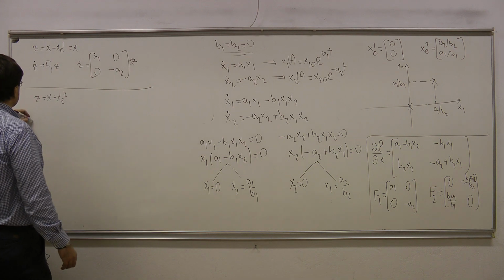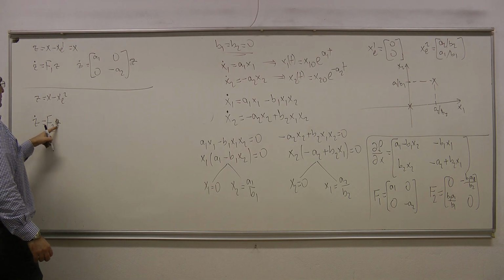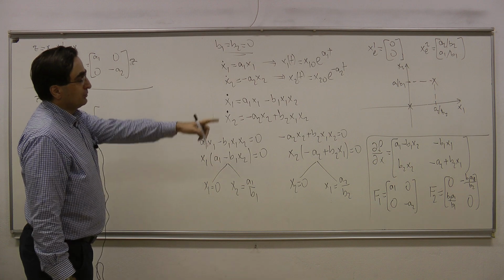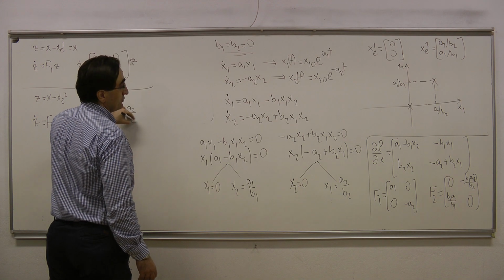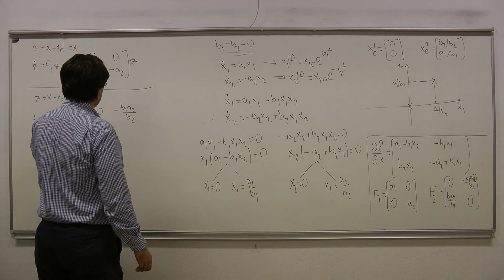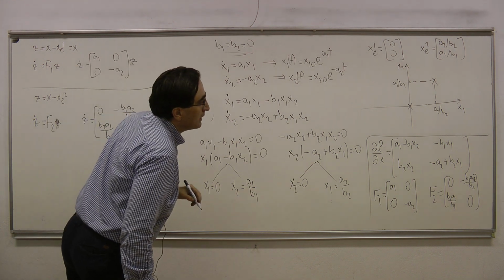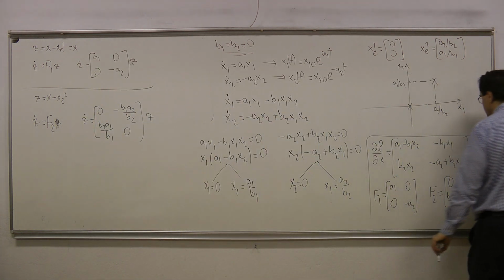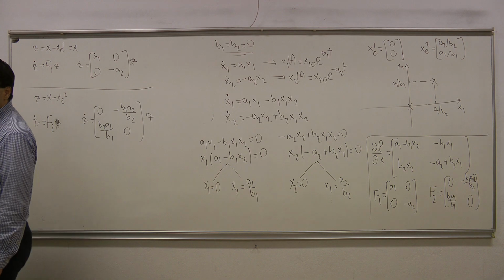What I have to do here is to write the dynamics around xe2, and that would be Z dot equals F2 Z, and we see here that F2 in that case would be 0, minus b1 a2 over b2, and b2 a1 over b1, and I would have 0 here, times Z. Okay. So these are the linearized systems around these equilibrium points.